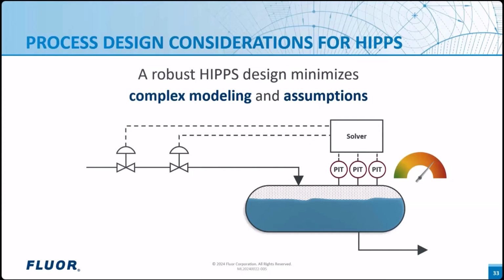To validate the functionality of this concept, assumptions would have to be made regarding the fill rate, heat transfer coefficients, and ambient conditions such as temperature and wind speed. As a result, the predictions by the dynamic model would only be as good as the heat transfer coefficients or other assumptions. Some concerns with this approach are also raised. The rate of pressure rise is a function of fill rate. A slow creeping fill rate can allow temperatures to equalize with ambient with no observable pressure rise.